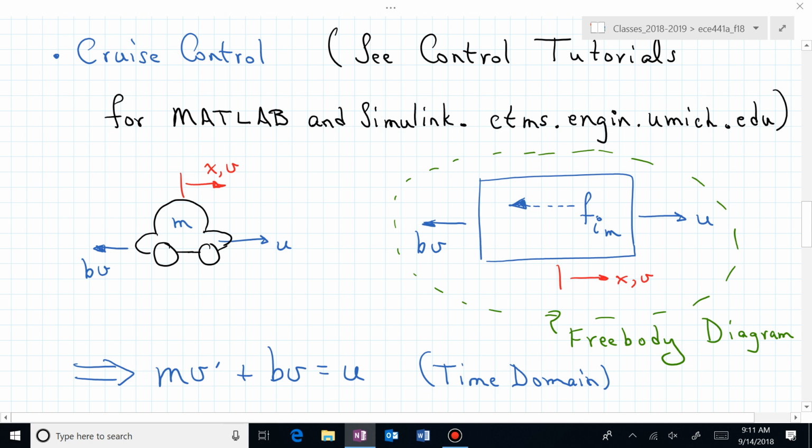And what else do we have if we're trying to model the dynamic behavior of that system, that vehicle? Now you can look to how I've conceptualized the car as a block. It's now a mass, and maybe I should have put a mass inside the block. And now if you wanted to try to push that block, that mass, in the positive x direction, you're going to have an inertial force that opposes that.